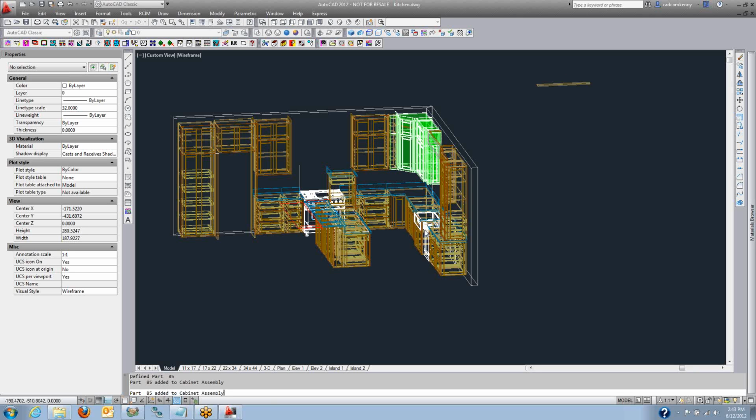You can also add additional features to the parts. When they're feature recognized, you can go back and add additional features like two-dimensional drilled holes or any other kind of geometry, or text to be engraved. You could put some text on there for the nesting program so you can see it when it's laid out on a nest. You can identify the part, although you'll see that Router-CIM also identifies the part by a part number. And at this point, it's just going to take a few more minutes for the feature recognition to complete, and all the parts will be feature recognized.